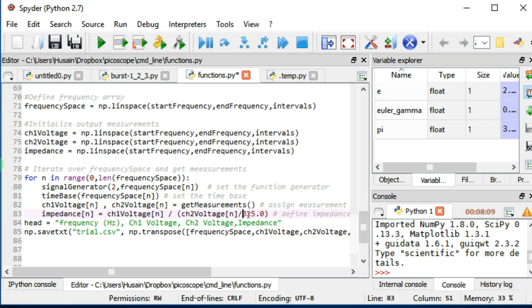value of the resistor. Now this resistor is not a non-inductive resistor. It will change its value with frequency, but this particular one, because it's a relatively low value of resistance, it's not going to change too much. So we're just going to assume for all practical purposes that it's going to remain at 325, just like it was using our multimeter in its measurement.